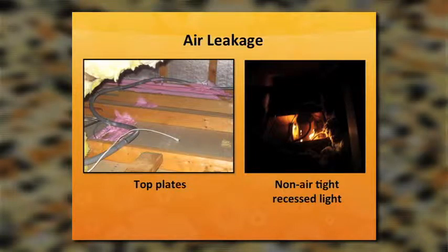This next picture we have is our recessed can light, and we can actually see, if you were to turn all your flashlights and everything off when you're in the attic doing an inspection, you can see glowing lights, and that glow is evidence that air can move through those can lights into the attic space itself.